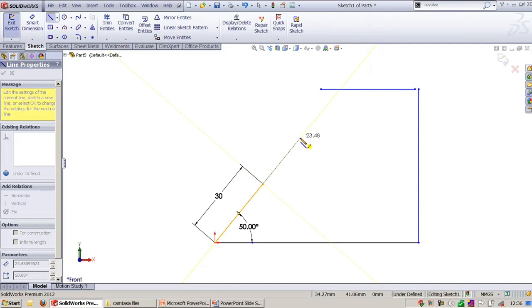There is one more thing I want to enlighten here. When you create a line segment, you can also create an arc continuing with that. Before that, let's complete this inferencing. You can see here when I move near any of the line segments, it will show you the end point, or I can drag from here to get this midpoint. Now I will show an example. From here I will get a point, and from here also you can see a midpoint you can choose. So this is what we call an inferencing point.